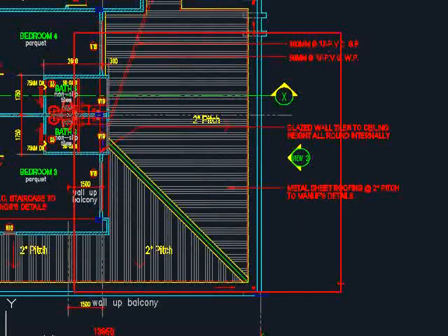And then some details of the roofings. What kind of material used for the roofing? Which in this case we are talking about the metal sheet roofing. The pitch angle is 2 degrees, and it also indicates to you the floor path so that you can imagine it in 3D. And there will be gutter to collect the water from the roof and divert the water to the rainwater down pipe to be discharged from the upper story to the lower story, and then to the perimeter drain to be discharged out of the building.